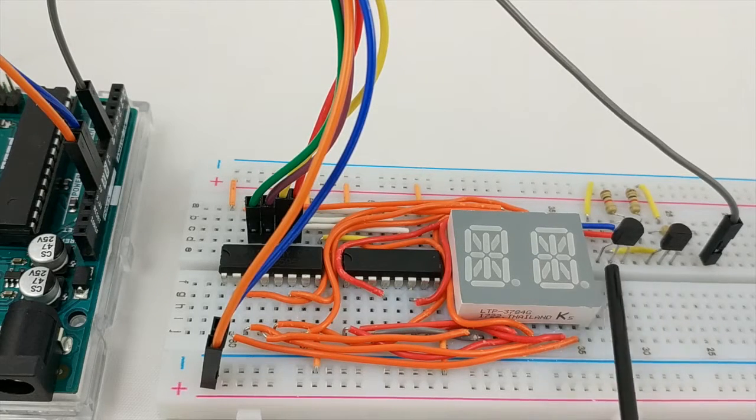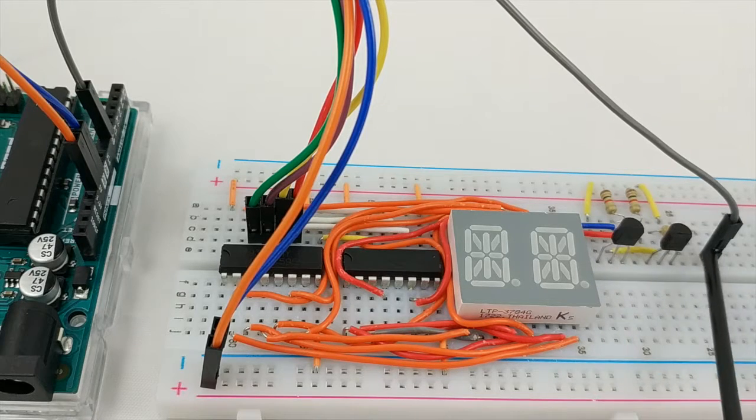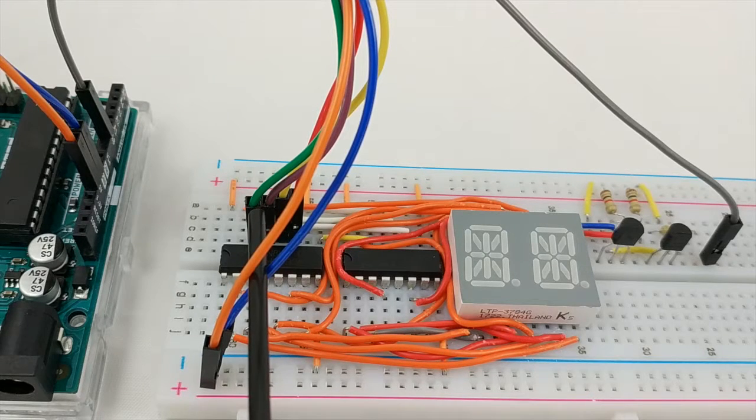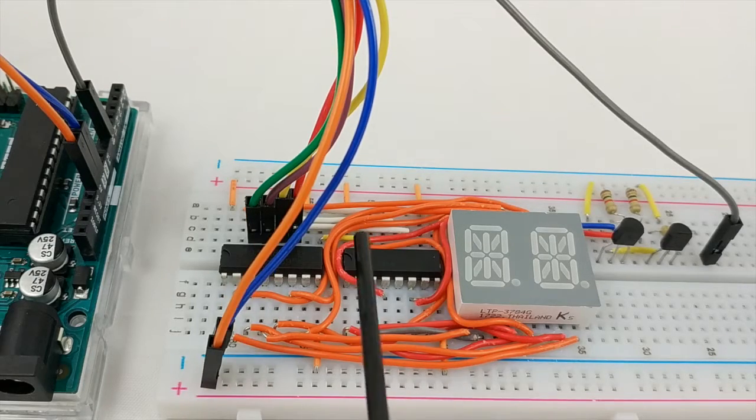The two shift registers' latch, clock, and output enable pins are connected to Arduino pins 10, 13, and 5 respectively. The shift registers' master reset pins are tied permanently to high, and the breadboard receives power and ground from the 5-volt and ground pins of the microcontroller.